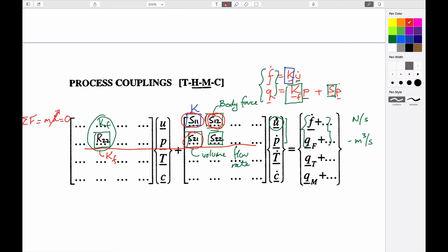One which operates on displacements, which is the coupling term, and the other one which operates on fluid pressures, which is the same as our storage term from previous, right, when we did groundwater flow equations. So in other words, this term here would be S22 that exists here. And in this flow equation, S21 doesn't exist. So the question is, S21, where is it? It doesn't exist. And so that's the term that we've added. So this is the expression we're trying to get.